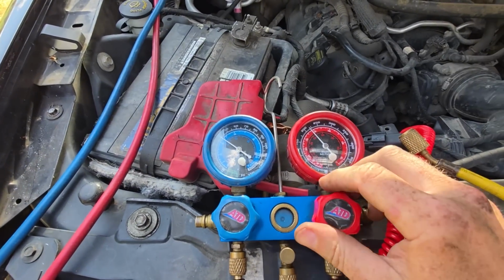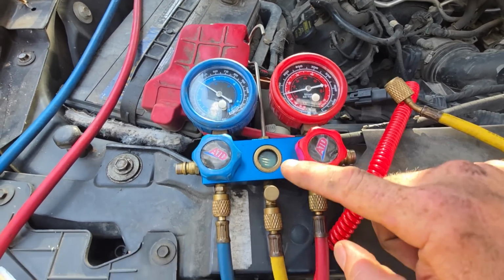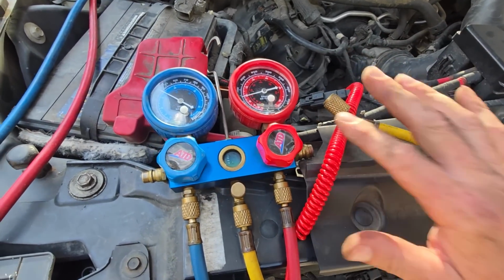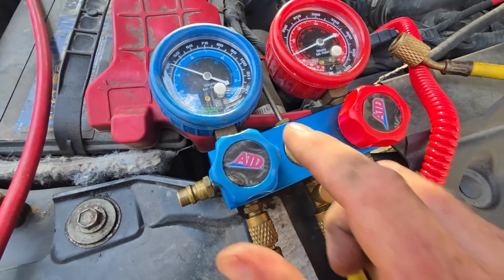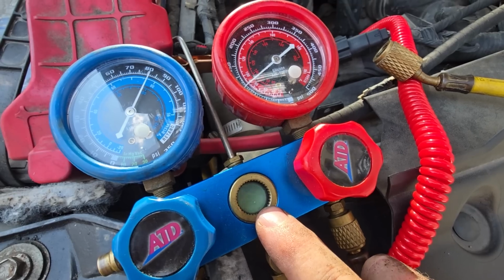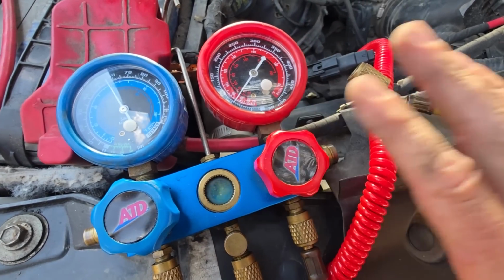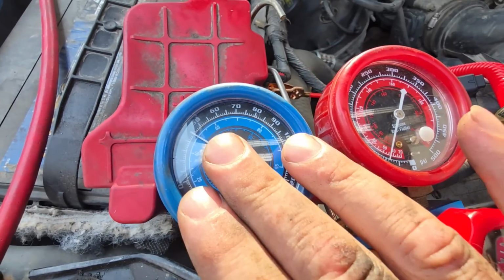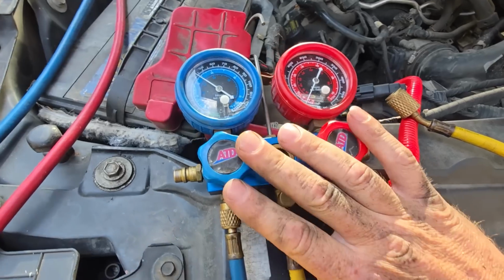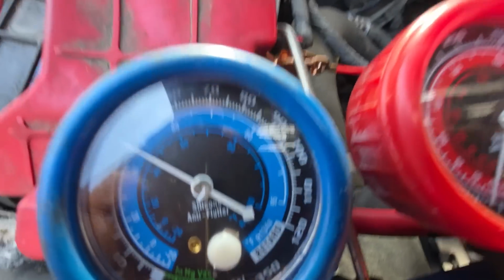So now when I open this valve, it pushes that high pressure, you see the dye in there and the oil, goes into the yellow hose, which is why it's important you have a check valve. So all that high pressure is trapped here. And now what I want to do is open the low side and I'm going to pull all of that out. All of that remaining refrigerant, oil, dye that was in his system that's trapped now in my red hose and yellow hose. I'm now pulling into the low side of his system, trapping probably 1 to 2 ounces of refrigerant that would be in your gauges. I'm pulling it back into the system.